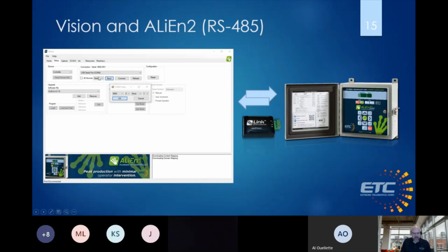So we're actually using a serial connection, and we're using this USB device. And we can actually click this baud button, and it gives me the settings. So the baud rate, the data, the parity, and the stop bits. So you can actually change this for different controllers if you want, or you can change the baud rate if you want to go faster. But the important thing in all Modbus communication is make sure that these serial settings on this side are the same as on the controller. And so you want to make sure you go in and change the Modbus settings to make sure that they're equivalent here. So once we've done that and we go connect, we've now established a connection.